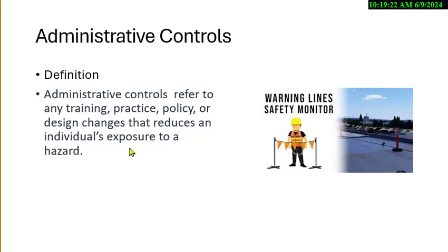And the industry came up with, we're going to use a monitor. We're going to have these flags at guardrail height, but they're not going to be as strong as a guardrail. They'll be on cones because we're going to move them. We'll put them 6 feet away, and behind that will be the monitor watching the workers at the edge.